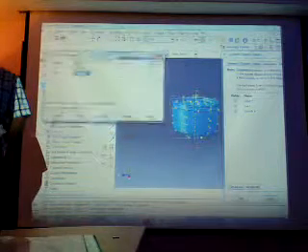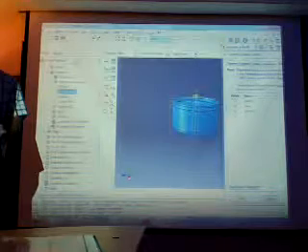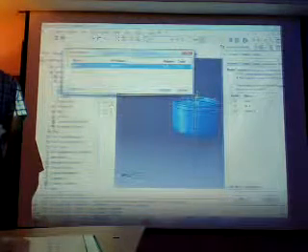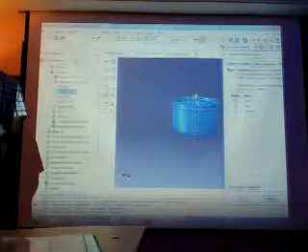Interaction now is completed, you can see. Here we have just inertia. Why? Because I passed the step module. If you create your step here, for example, as explicit dynamic, continue, okay. In the interaction, you can see it's automatically propagated for step 1.